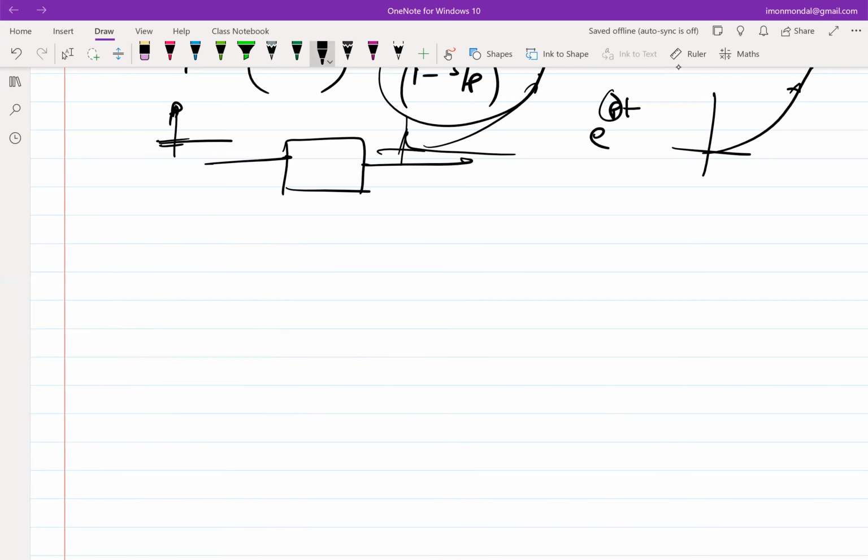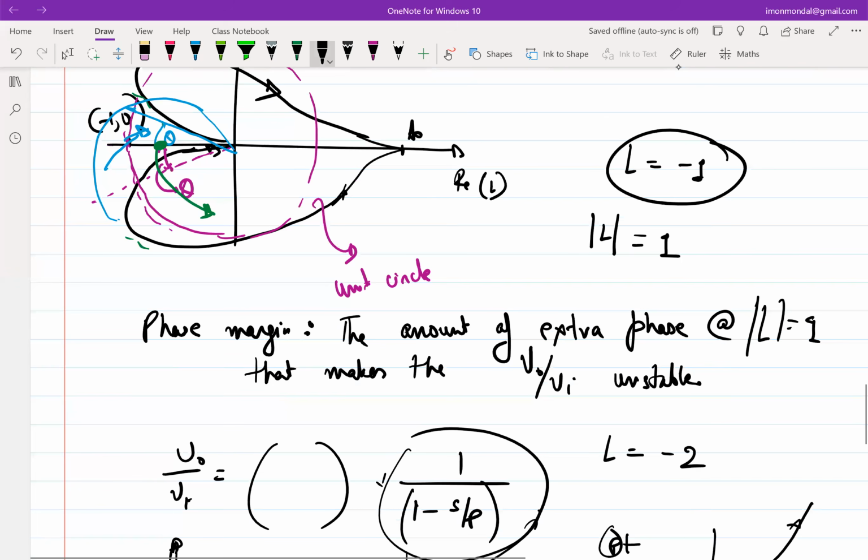So the key thing that we are trying to focus on, I hope I answered your question, or I hope it didn't confuse you further. Also, when the pole is at -1, the graph passes through it, because the pole is alone there. Yes, so that is marginally unstable. Right. When you go to -1 it is unstable. That is also, the terminology is marginally unstable. So that's the terminology. You can consider it to be unstable. Forget about marginal, either unstable or stable. That is also unstable. Okay.